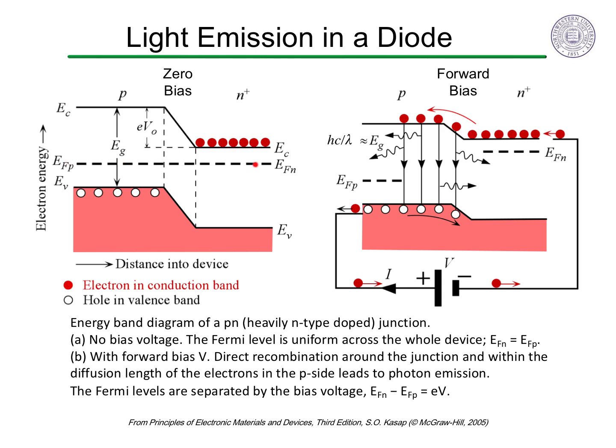To have the Fermi level near the valence band on the P side and near the conduction band on the N-type side requires that the bands have been bent due to the built-in voltage. The built-in voltage V0 also acts as a barrier to charge transport, preventing the diffusion of electrons or holes to the other side.